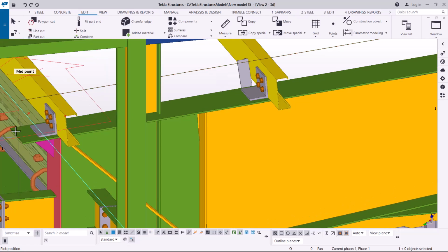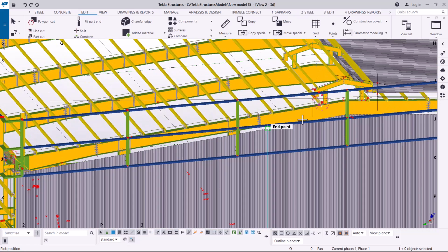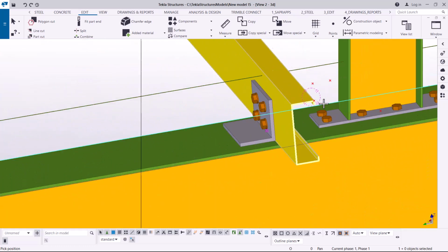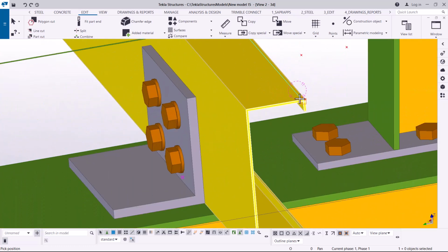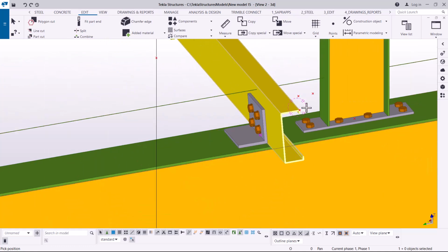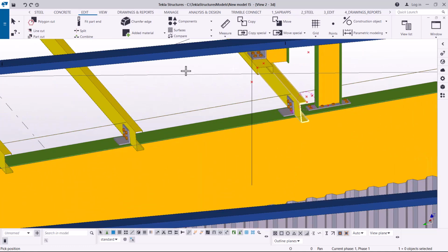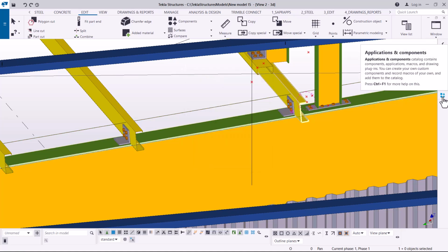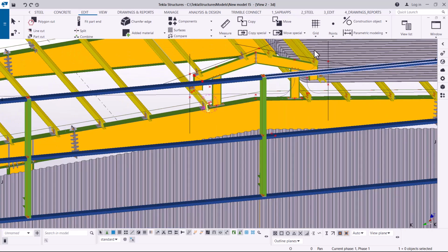Now I've created a point there, and if I zoom out and come here, I've also created a point there and offsetted that point slightly upward by 50 millimeter. Then from here, I took it up by 400 up to here. Now we want to create a rod that will help us in taking the curved shape of the crimped sheet like that.